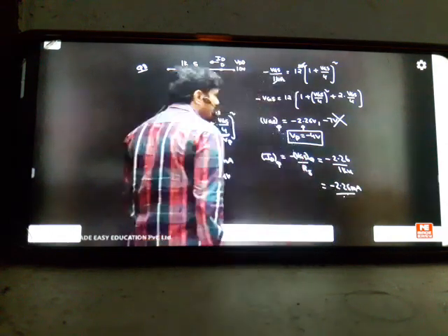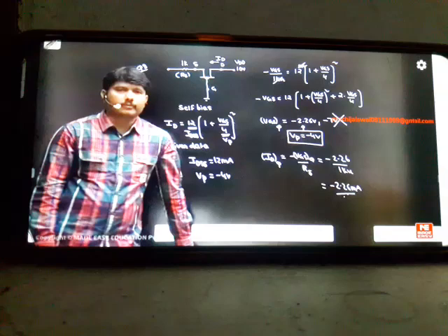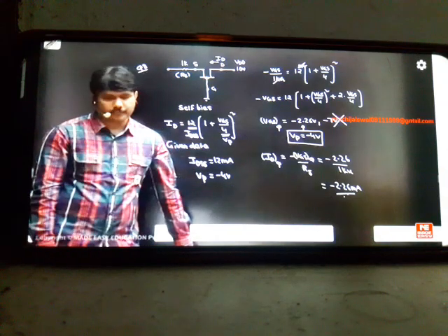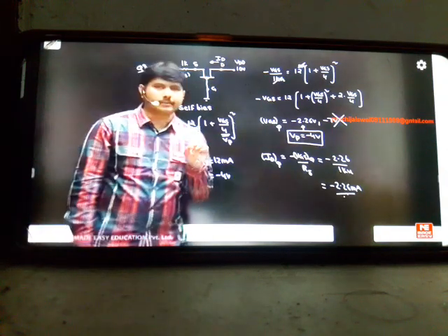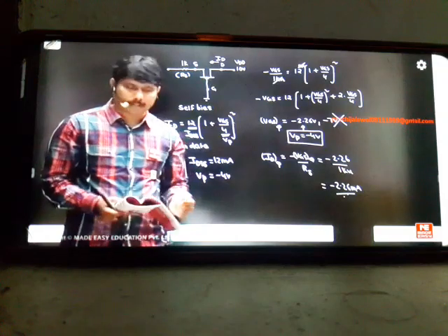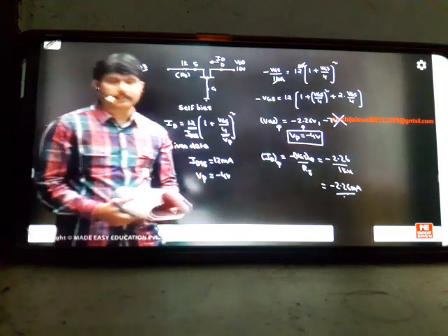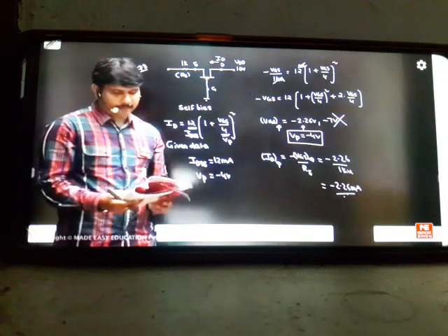So this is the way I do the problems by the quadratic method. If a question comes like this, this is how to tackle the problem using yesterday's class quadratic mathematics. You'll get two root values. Of those you have to justify one answer. After getting that answer, you find the operating current IDQ by the Ohm's law technique. It will be completed. Like this they can also ask you questions. This is the best example for it.